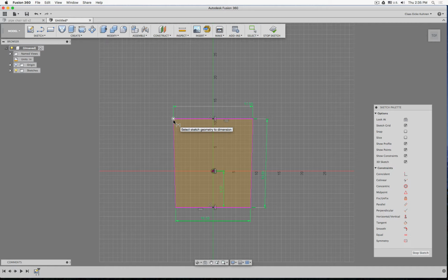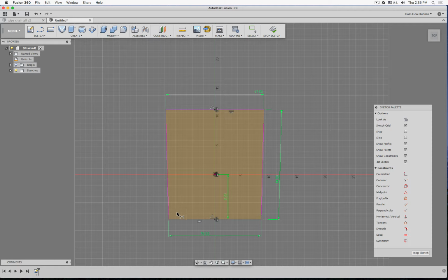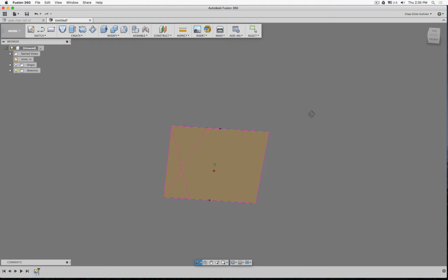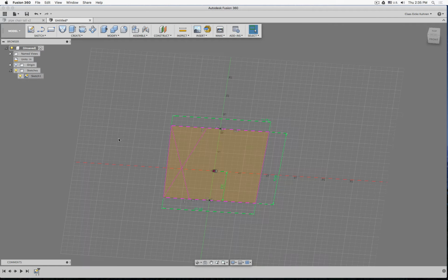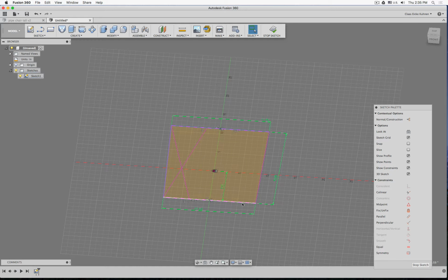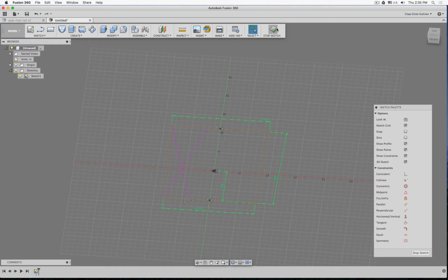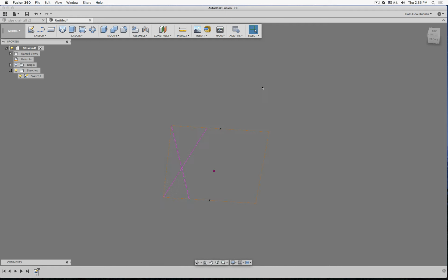Now the pipes will be rotated, so we need to create inside the sketch a little bit of geometry that can help us with that. So maybe one line there and maybe one line there. Okay, perfect, good. If we want to make this a little bit more readable, we just make this into construction lines there. So let's maybe start with the front leg.